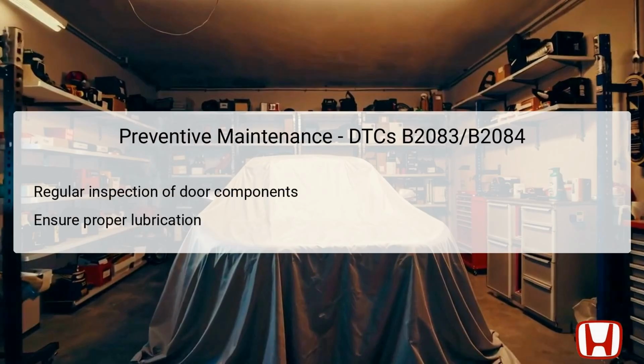To maintain the integrity of the power sliding door system and prevent future issues related to DTCs B2083 and B2084, regular preventive maintenance is essential. Routine inspections of the door components can identify wear and tear before it leads to system failures. Checking the functionality of the power sliding door control unit and associated wiring for any signs of fraying or damage will prolong the lifespan of the system.